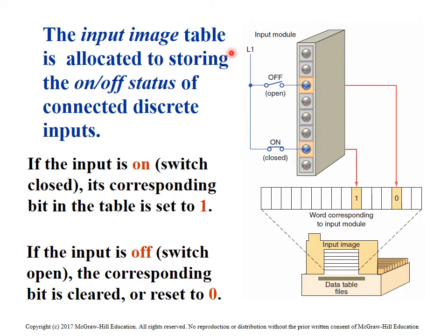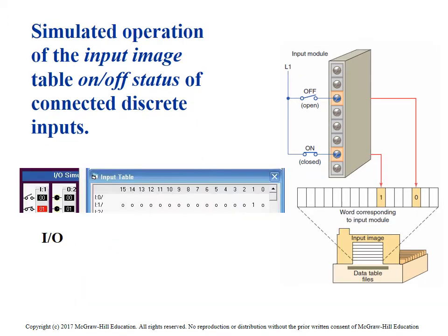Okay. The next location we're looking at here is 0, 1, 2, 3, 4, 5, 6. Bit number 6. So if I'm looking at bit number 6 as being on, I can go over here 0, 1, 2, 3, 4, 5, 6. And that shows us that location being on. So here we're seeing that input actually turn on and off.